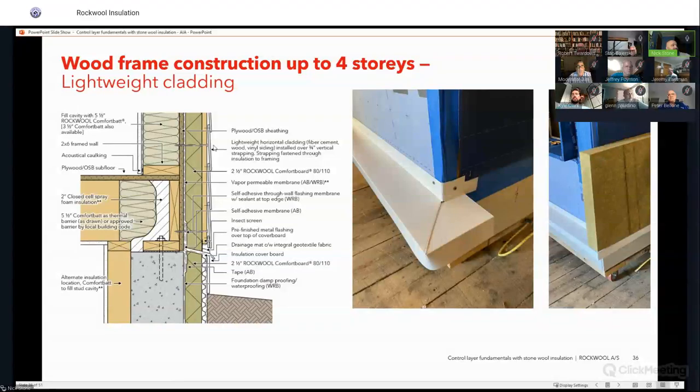When it comes to fasteners, I'm not sure if you guys get into this or not, but number 9 deck screws, when it comes to exterior insulation, are really that perfect sweet spot. They have enough moment and shear strength back here at the sheathing location that you're not going to have issues shearing those fasteners, but they're still economical enough to keep the contractors up and moving. So those number 9 fasteners work out really well for doing exterior insulation.